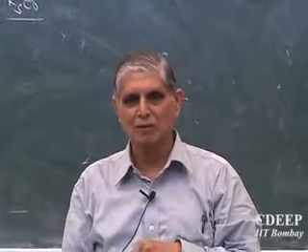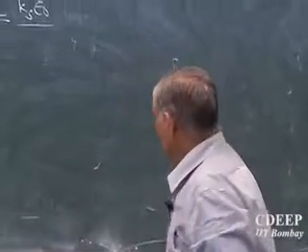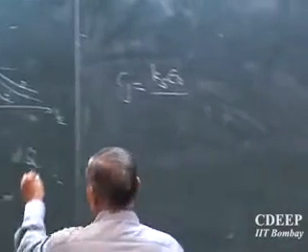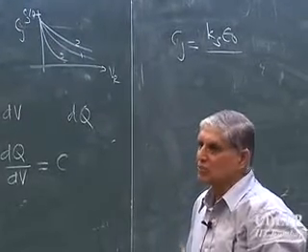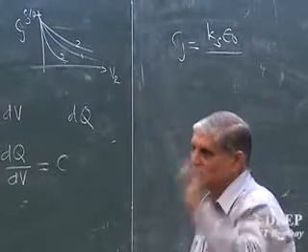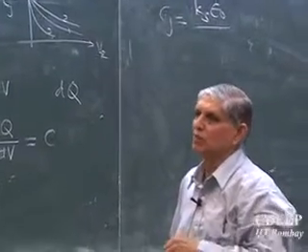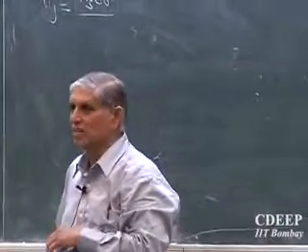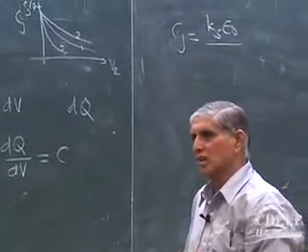So area we normally initially don't use anywhere. The reason is that this Q is charge density, charge per unit area. Is that correct? It's charge per unit area, so you will also get capacitance per unit area. So normally, unless specified, it is farad per centimeter square. If I give you area, then you can as well calculate farad.